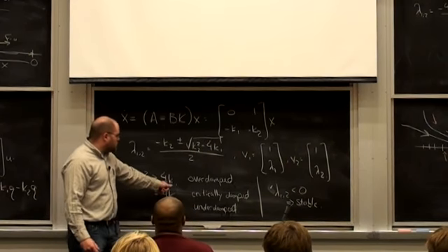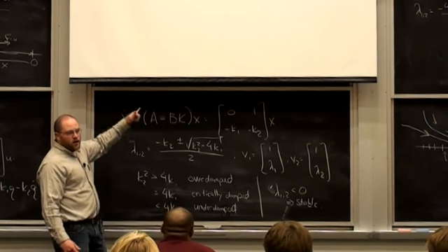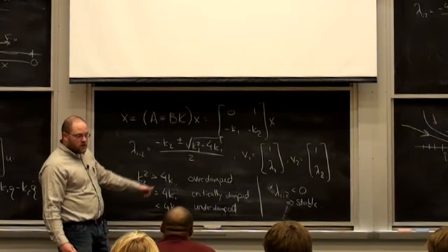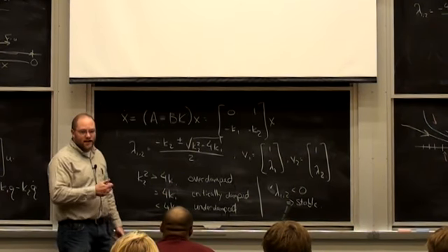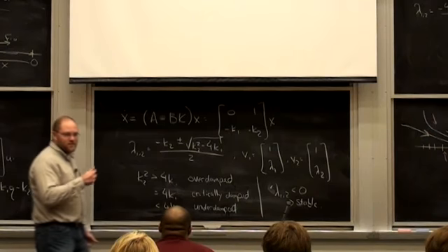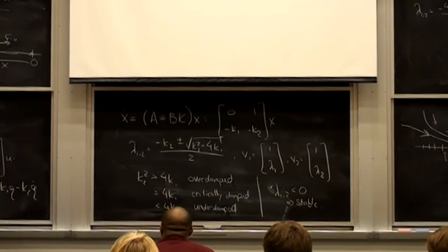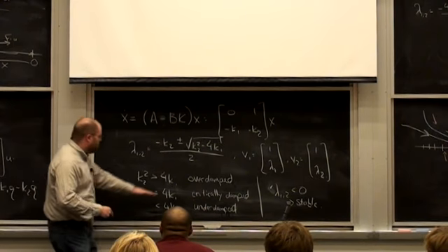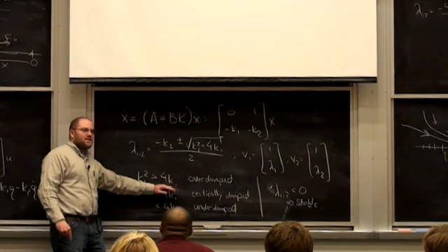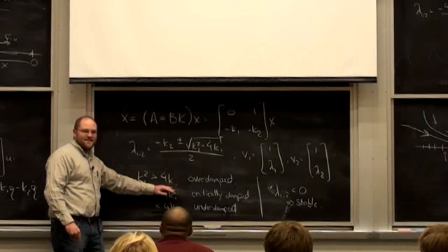And I can just start driving K1 and correspondingly K2 up as high as I like, right? And make the system get to the origin as fast as I want, and it won't oscillate, right? So what's my motive? Why not just drive them all the way to infinity? You don't have a motor that can do that?